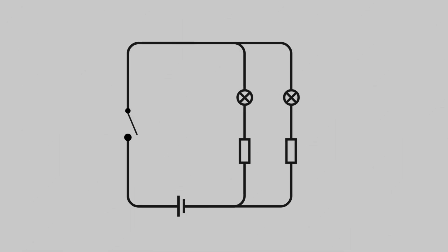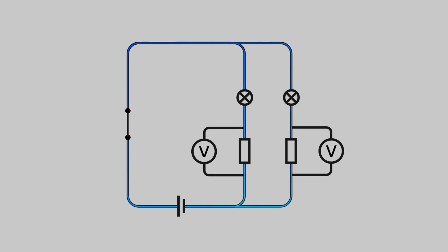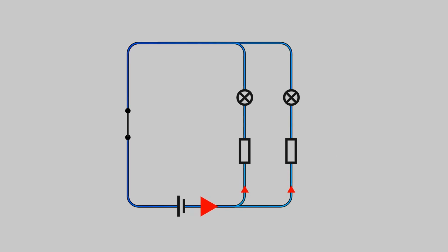Laws governing parallel circuits. In this case, there is more than one path that current can flow through. In the example we have here, there are 2 resistors. One is 22 ohms and the other is 100 ohms. When voltage across each is measured, it will be the same because they are supplied with the same amount of voltage. When measuring the current flow, however, we will see that the total current will be larger than the 2 individual current flows, but will be equal to the sum of the current flows. The current through the smaller resistor will be larger than current through the larger resistor.